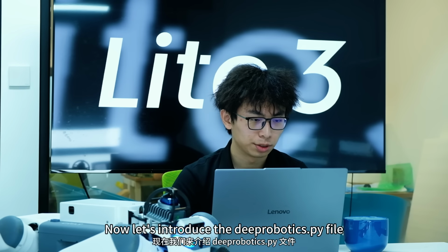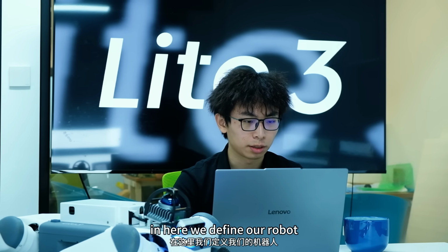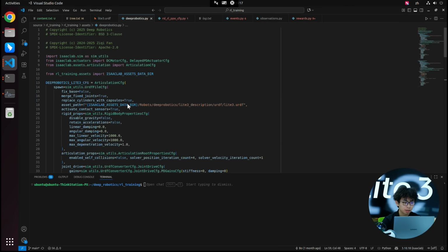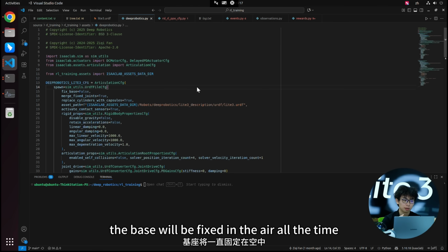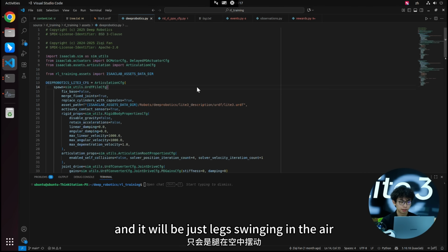Now let's introduce the deep robotics py file. In here we define our robot. So I'm going to introduce the important parameters here. So let's go from the start. This fixed base is where we define whether the base will be fixed or not. If it is true, the base will be fixed in the air all the time. You cannot move it. And it will be just legs swinging in the air.